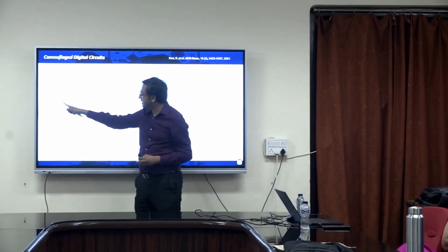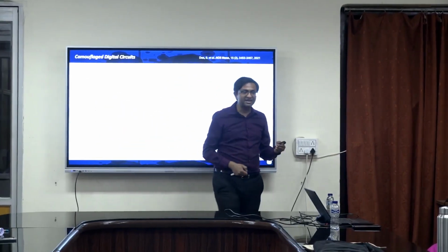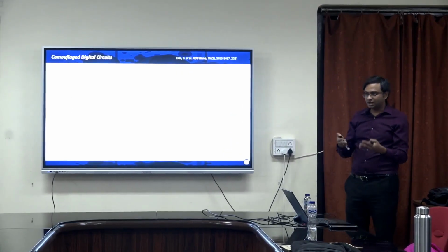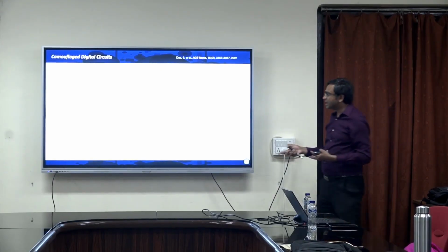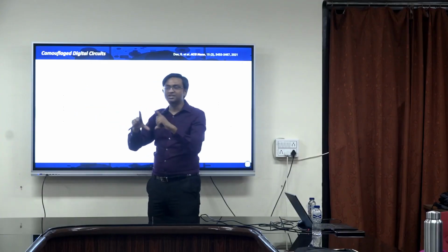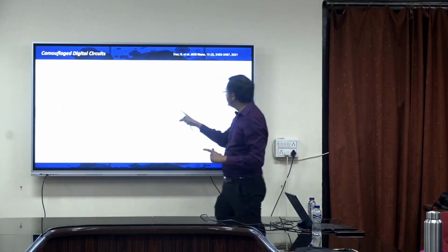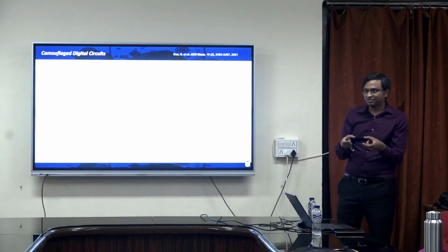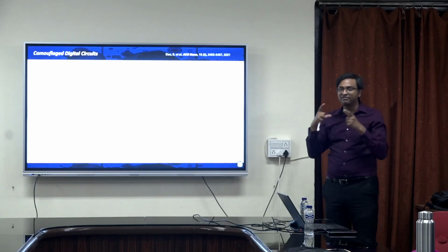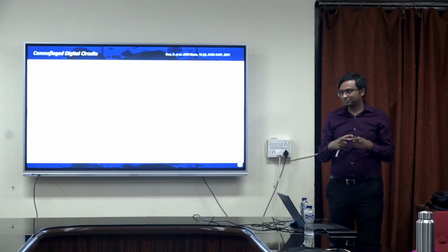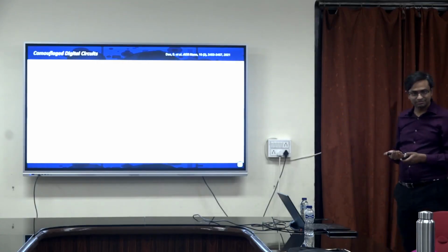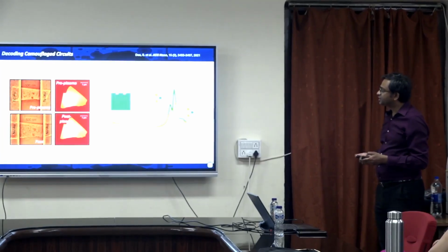If I create a circuit like this, because all our AND gate, OR gate, XOR gate have a particular structure, right? How they are arranged, correct? But now, if these are all kind of question marks, I can use a generic structure, and then I can create individual gates. So therefore, the OR gate, XOR gate, NOR gate, XNOR gate, everything is going to look alike, right? So I can completely fool my reverse engineer. That's the thing that we are trying to do.